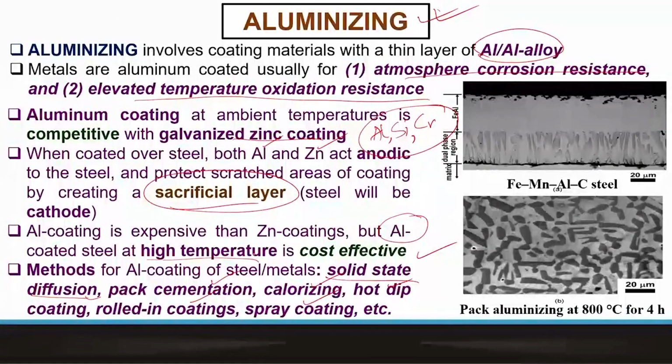So following the diffusional process, the coating is created. We are now seeing about half a millimeter, or 0.2, 0.3, up to about 0.5 millimeter thick coatings. These coatings have a top layer. If you just look at the surface, there's no etching here because this is primarily an Fe3Al layer, a highly protective, highly corrosion resistant, iron aluminide rich layer. Then we'll have a diffusional zone.